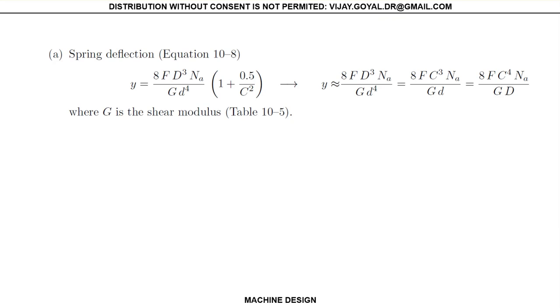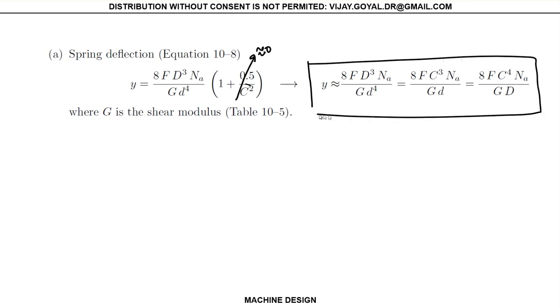We also have something we call the spring deflection, and I'm going to tell you where this term comes from later. Right now, your y is given by this, and typically this number is very large, so this term is almost close to zero. We can ignore this term, and that's why you find these typical expressions in many different textbooks, with variations depending on what you really want to design.